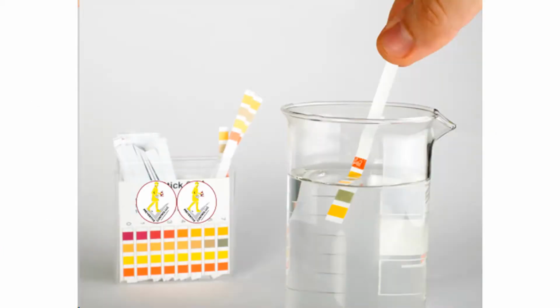In most cases, the chemical concentration of the chemical solution can be measured using a test strip that changes color when it is exposed to the chemical. Always follow the instructions for using each test strip kit. Comparing the color on the test strips allows you to perform a quick check if the concentration of the chemical you are using is within the requirements.